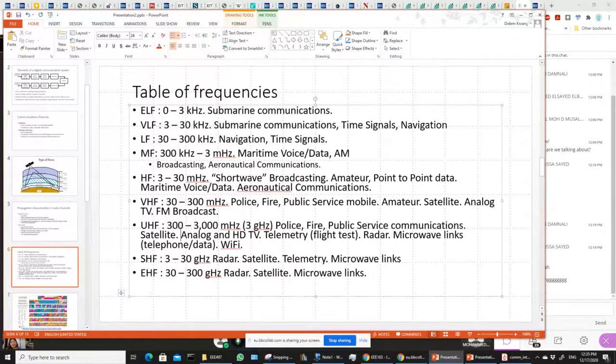So now they're going to use 60 gigahertz, but with many antennas. In fact, massive MIMO is what we call it. There are a massive number of antennas for a single or for multiple links, but the number of antennas is going to be bigger than the number of users. So that's the plan. The base station will have like 500 antennas, and they expect that base station to have maybe 100 users. Then you can have 5 antennas per user, and if the user is close to the base station, it's only going to need 1 or 2 antennas. But a user which is far away from the base station might use more of the antennas.